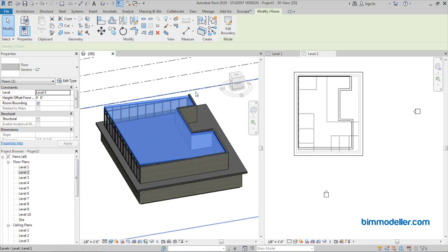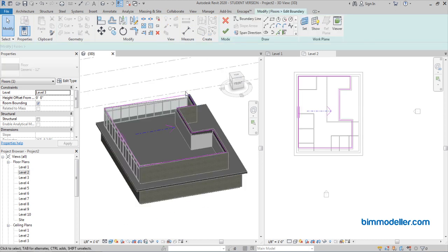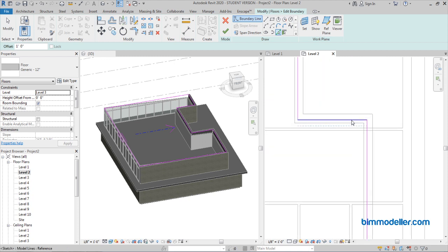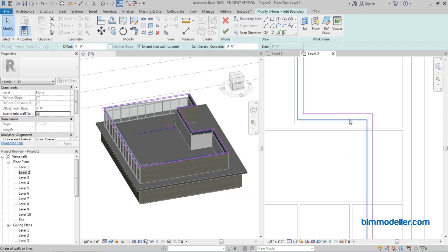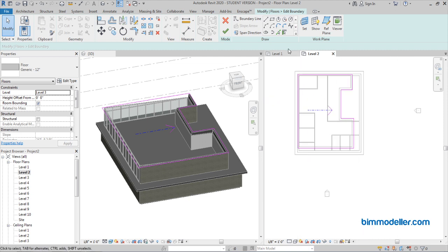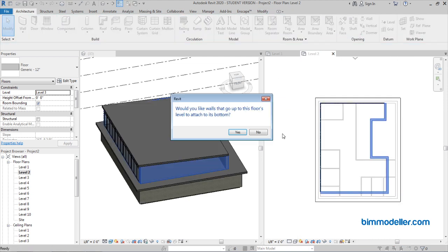I'd like to extend the floors so that we can see the edges outside, so that rain will fall outside of the floor. So I can go back to the pick option and say offset value 1 feet, and I have to select these lines to offset. I'm using tab to select the continuous selection, and I will be able to use the tab and select it and delete the already existing lines, finishing it.